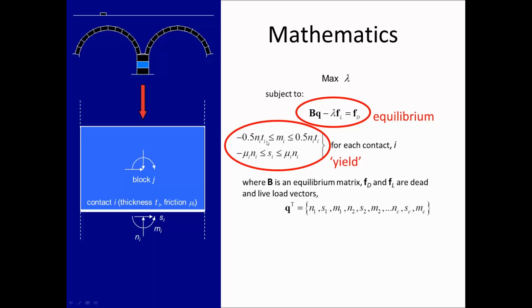And the top yield constraint that we can see here in the elliptical region is actually a shear constraint. So actually the second one is a shear constraint. The top one is actually a rocking constraint. In this particular case, for simplicity, assuming that we have infinite crushing resistance.